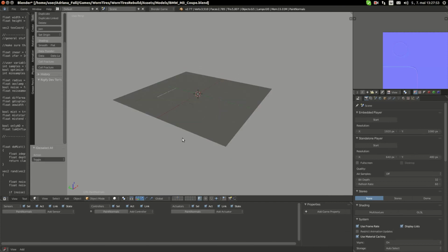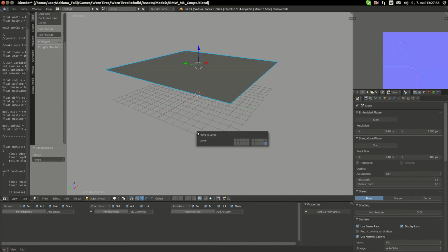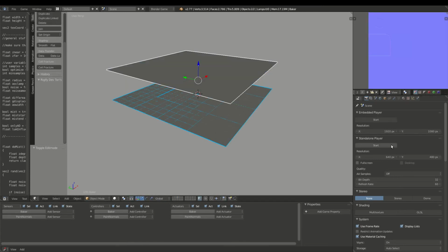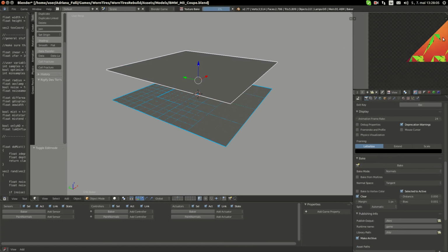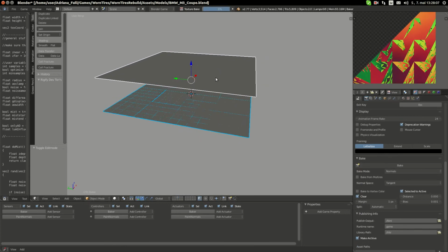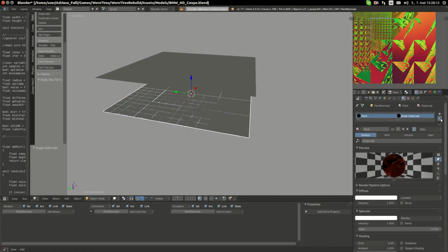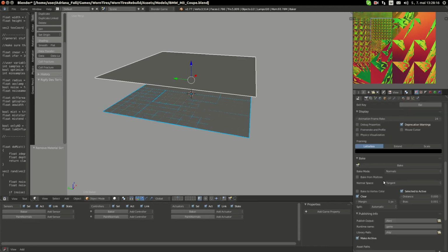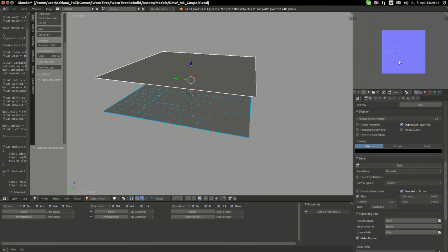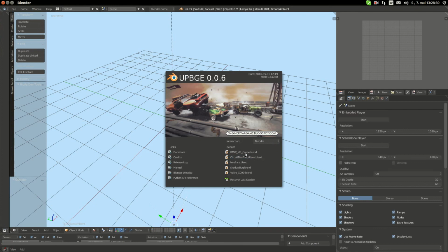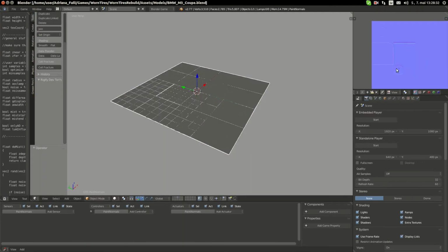I use it most of the time, but sometimes it's not working well for some modeling works. One of the cases is this, which is normal speed. Okay, it's acting with circular something. It's because we've got a paint material on this. Let's remove it, because the paint material uses the normals, and it's working well now. Image, save as, just save image. You can open it up back in the previous version, and we've got this updated texture here.